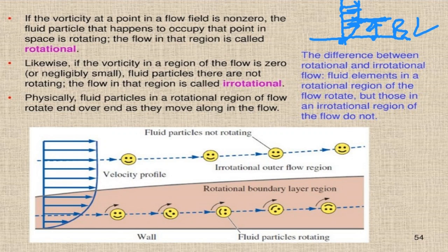And above the boundary layer, the fluid particles do not have any information that there is a plate there. So the information, because of the viscosity, can be transferred only within the boundary layer thickness. It can be just a few millimeters, but in atmospheric phenomena, it can be 100 meters. Around a ship, it can be 20 centimeters, whatever.